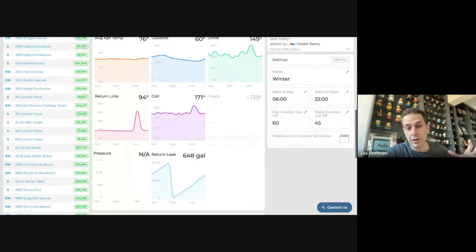If there's water, the easiest thing to do is have the plumber replace the pipe that's clearly leaking, that's visible. See how much that moves the return line leak down. If that fixes it, great, you're in great shape. If you have already fixed them or you don't see any water, it gets a little bit more tricky.